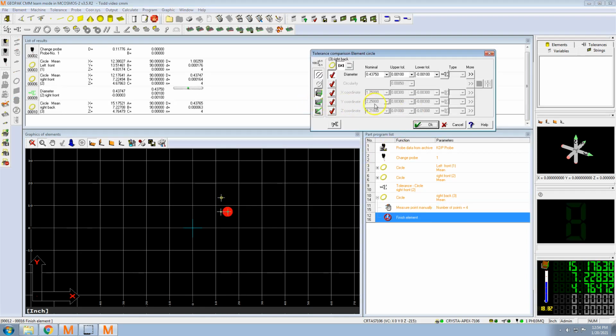Okay, now it's asking me for another tolerance block, because you want to tolerance every dimension you take if you're writing a program to measure multiples of parts. So again, it is 43765. It's going to leave whatever you put in there for the last tolerance block. Let's say this one right here was a lot tighter one. So it was 0.0001. So it had to be lapped minus.